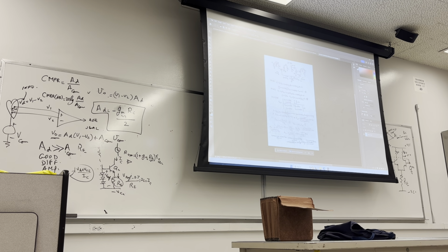So here, finally we calculate, yes, that shows the calculation. The differential gain is 13.5, it's just there. CMRR is the ratio of these two, 2,385. 20 log, about 67 decibels.